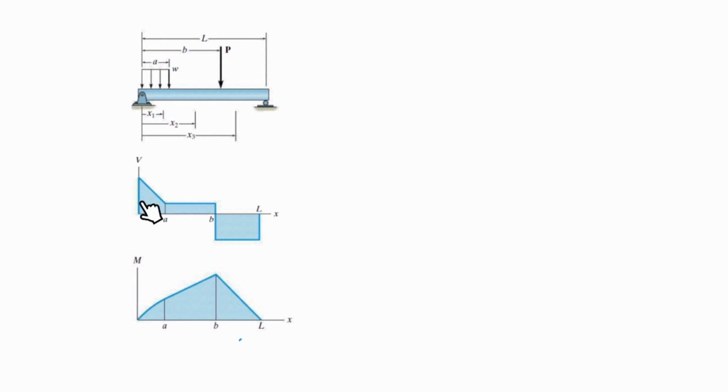For example, here I have the maximum shear. I can consider that if we are interested in designing based on shear, and here we can consider the bending moment. Usually it is the bending moment which causes the whole system to fail, and that's why we are very interested in going from V to M and finding the maximum moment applied on the system.